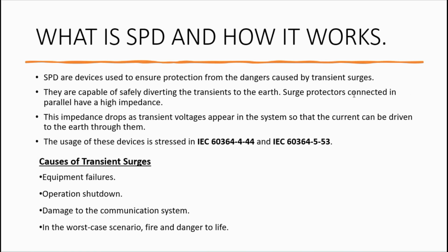What is the surge protection device? If we are discussing protection, there is a lot of protection in electrical systems related to relays and circuit breakers. Specifically, a circuit breaker provides short circuit protection and overcurrent protection. But what about the voltages? What about the transients coming in the voltages? Harmonics and transients. For that, we specifically turn to the SPD, which is the surge protection device.